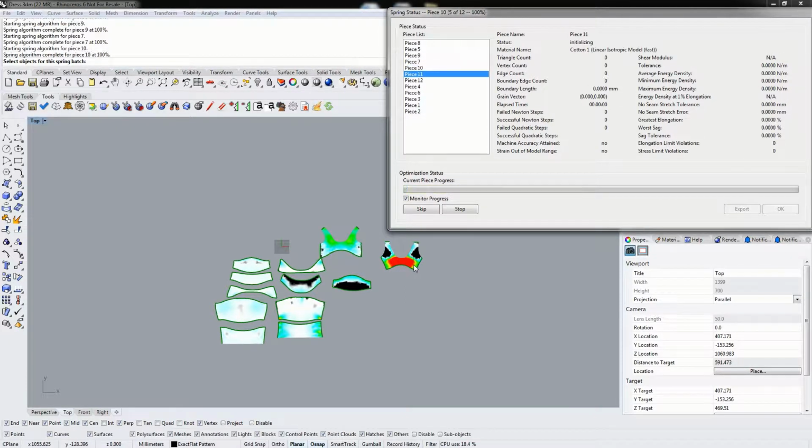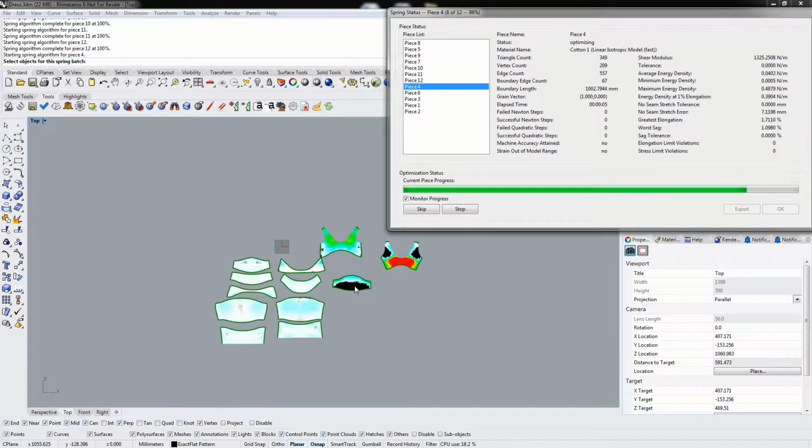We're reducing the amount of strain on the pattern piece, or the amount that we have to stretch or pull that pattern piece to get it to fit back onto the rigid shell. In the case of the areas where it's black, we're going to be removing material because black indicates sag or an excess of material. So we're going to be removing some of that material to allow the pattern piece to fit onto the 3D model without any kind of excess sagging or wrinkling.